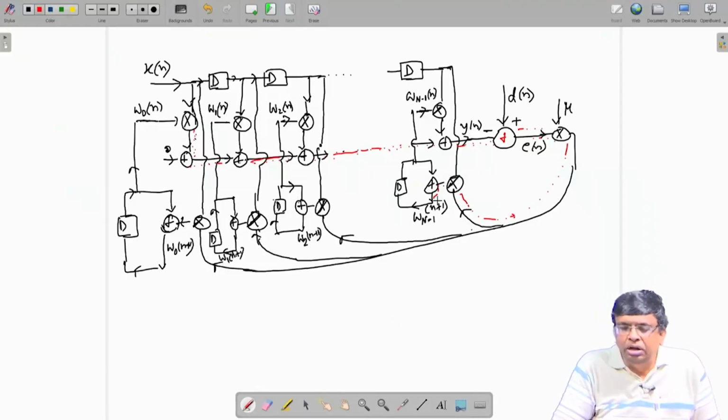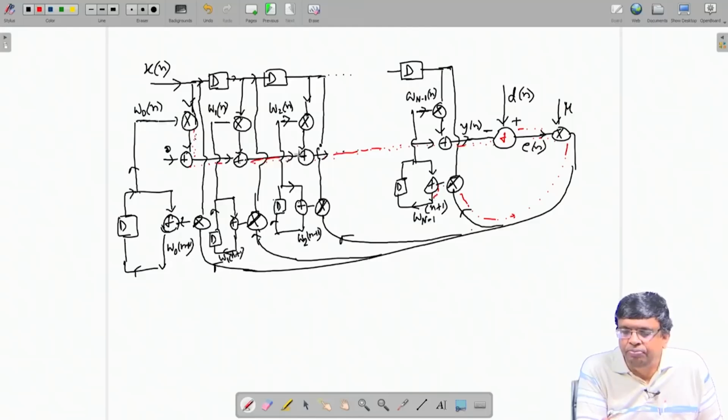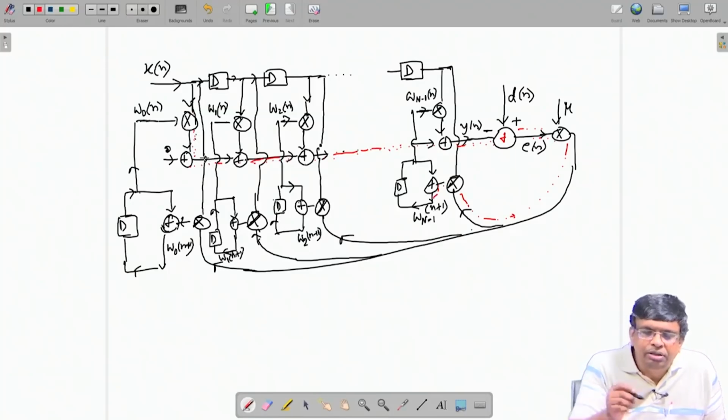I want to bring down the critical path. I want to, like an FIR filter retiming, here also in the adder chain, all the additions they are coming one after another in the same cycle. So, I want to insert delay here. If you want to insert delay here, I will try to do cut set retiming. So, what I will do, here I want a delay.